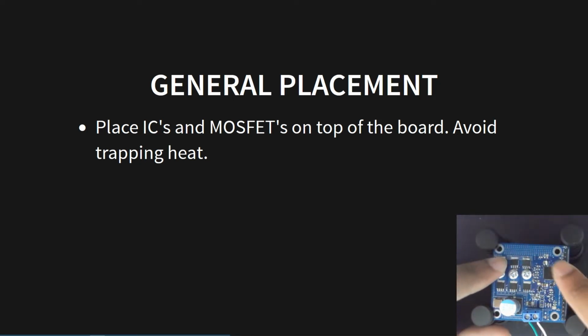So that's a general placement of making sure that the components that are generating heat, which could be the pre-driver and the MOSFET, are all on the upside so that the heat can dissipate freely.